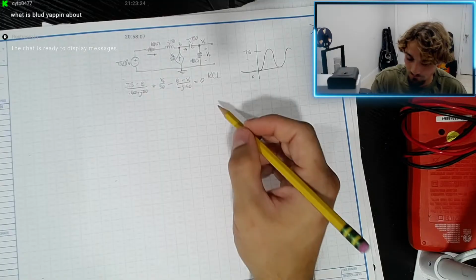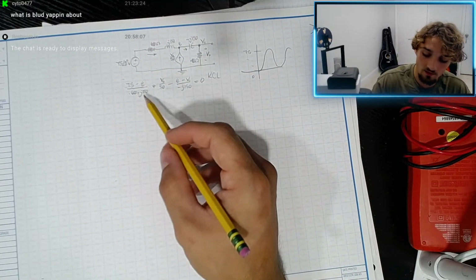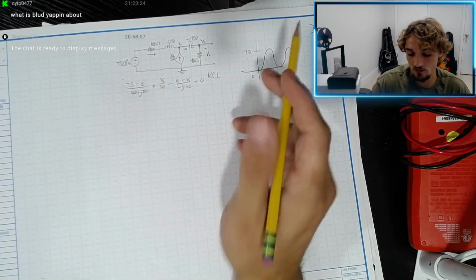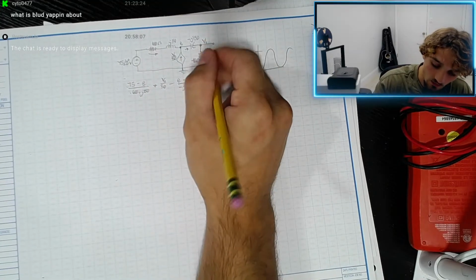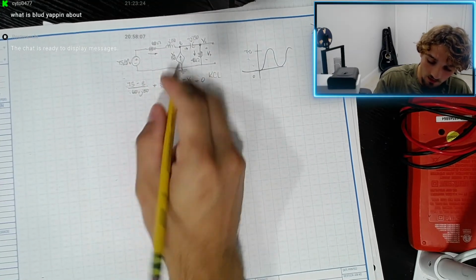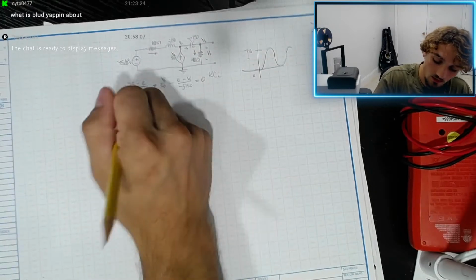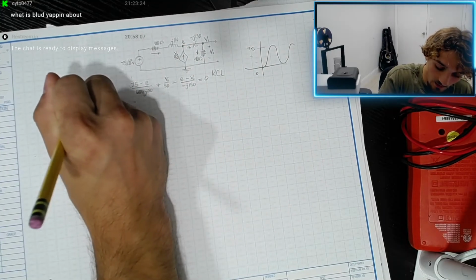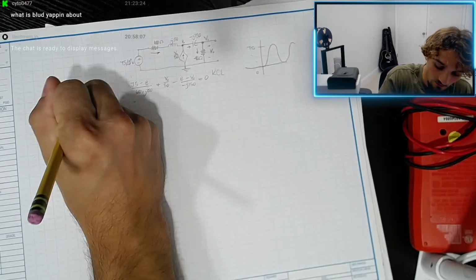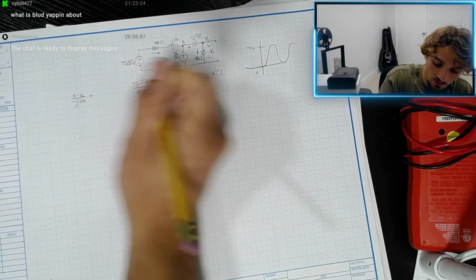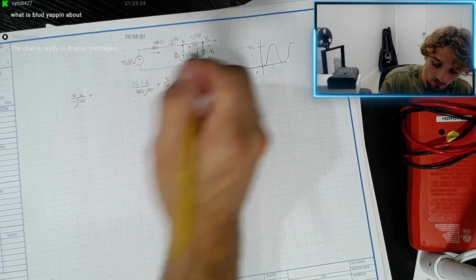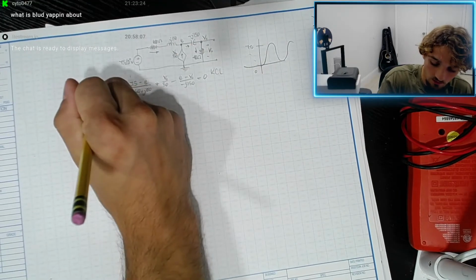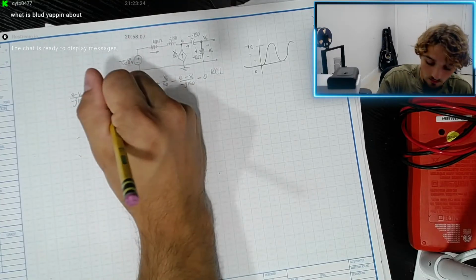All right, and then my other equation, because we have E and V out, these are our two unknown variables, therefore we need two equations to solve, okay? And so V out would equal, and the current is going to go in this direction, I'll write it over here: E minus V out divided by negative J150, plus, well, minus V out divided by 40 equals 0, right?